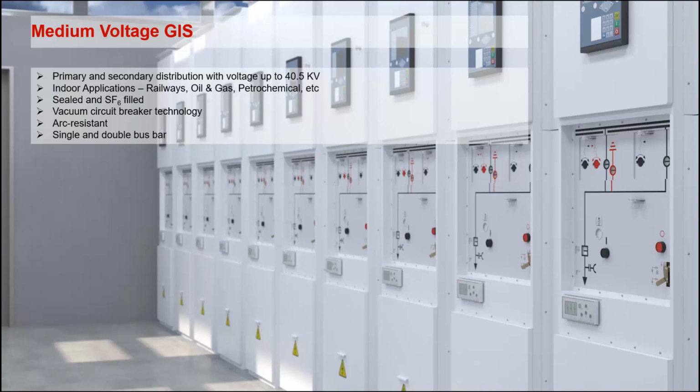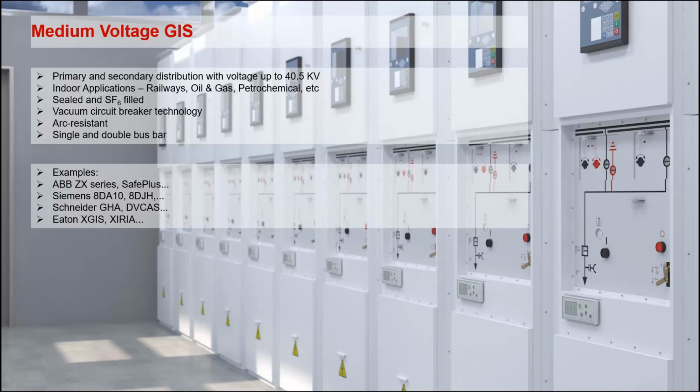The breaker technology used in these breakers is vacuum. So even though it is filled with SF6, the breaking technology used inside is vacuum. They have very high arc resistance because of the SF6 filled interiors. And you can have different configurations like single bus bar, double bus bar, and then there are a few examples from different vendors, such as ABB has ZX series for the primary distribution and SafePlus for the secondary distribution. Similarly, there are equivalent offerings from Siemens, Schneider, Eaton. So the idea of my presentation is not to give you details of these GIS, but to mainly look at the testing part of it.